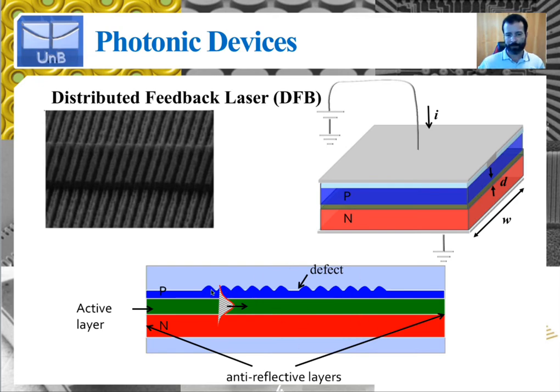You'd have a grating, a periodic corrugated structure, which in this case is the p-type semiconductor here. The period of the grating would be related to the Bragg wavelength, so there are specific equations used to design this grating in order for the high reflectivity to happen for a given Bragg wavelength, lambda b. But so you have this corrugated structure here, and light propagates in the active region as we've seen. So the mode is going to perceive this variation in the refractive indices between the region where you have the peaks in the corrugated structure and the valleys, and therefore effectively it will be as if this structure were similar to the multi-layer film structure that we talked about, although it's not strictly the same thing, right?